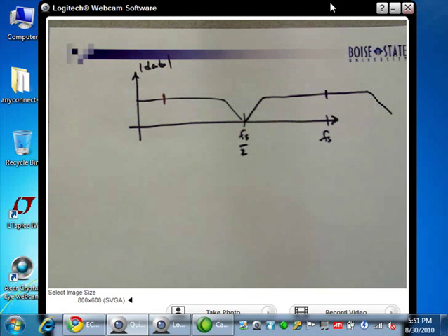Okay, you pass it through the filter, remove the frequency components, and then does anybody know what the sample rate is on a CD, for example? F sub s? No, it's 44.1 kilohertz. You know it's got to be greater than 20 kilohertz because they want to have good fidelity in the audio spectrum, right? So you can't go any lower than that, but you can imagine when you're recording music or saving music, you don't want to record it at 44 kilohertz. You want to record it much higher because you get a better signal to noise ratio, but then when you store it, you want it to go down.